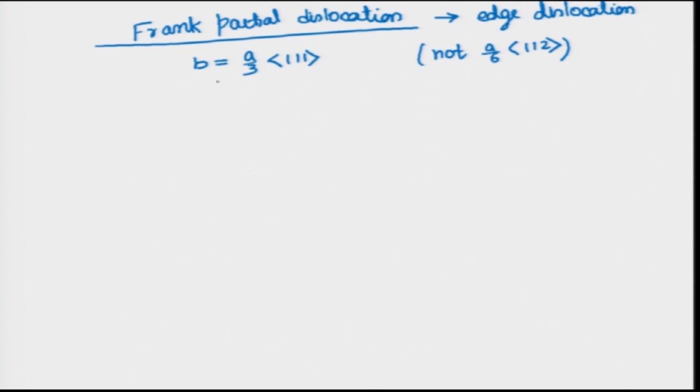and that is why we have not included it here, but we include it as a different type of partial Burgers vector, and it is called Frank partial dislocation. Why it is different, we will come to that in a moment, but for now this is possible in 4 different configurations, or there are 4 different vectors which have this type of Burgers vectors, and these are, you guessed it right, A alpha, B beta, C gamma and D delta.